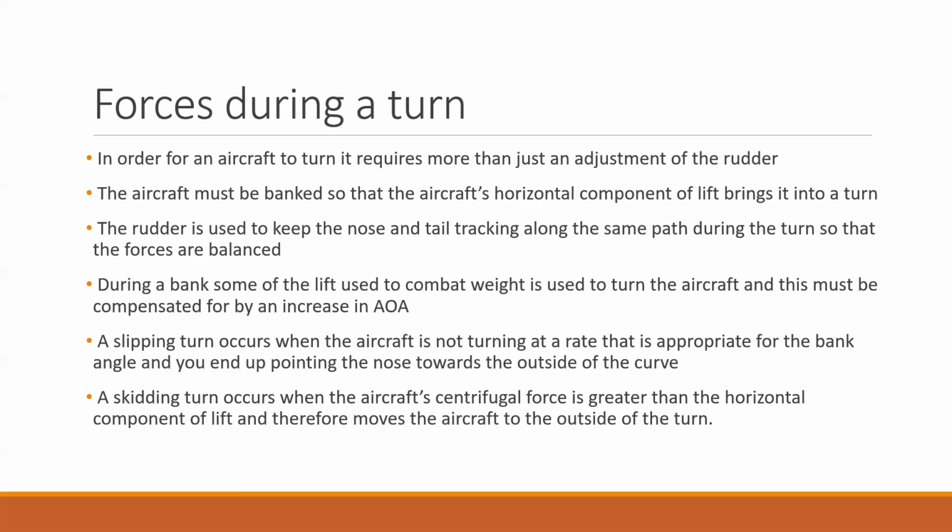The other type is a skidding turn, and this is where the aircraft moves towards the outside of the turn. So the nose is going to be pointing towards the inside of the turn. And again, you counteract this with your rudder pedals.